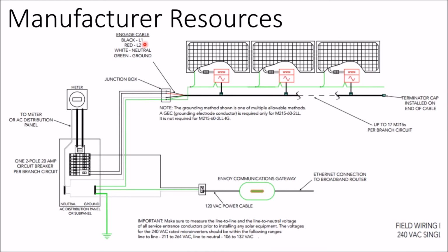And then I have leg one, leg two of power, and I see I'm also pulling up a neutral and also pulling up a ground. DC systems don't have neutrals, but you're probably still going to pull a neutral up to this junction box because that neutral circuit is also used as a communication circuit. And so if you're trying to trigger a rapid shutdown combiner box on a DC system, you still need that neutral wire there for communication. And then your system ground, of course.